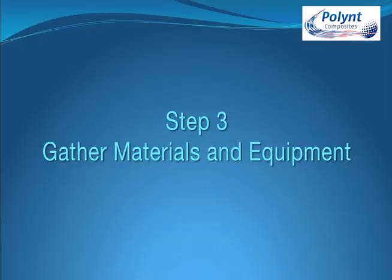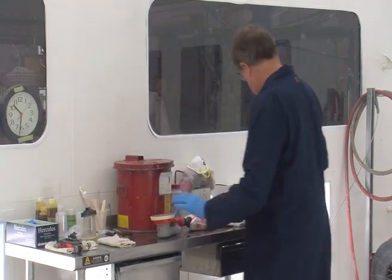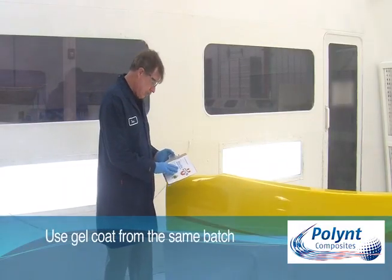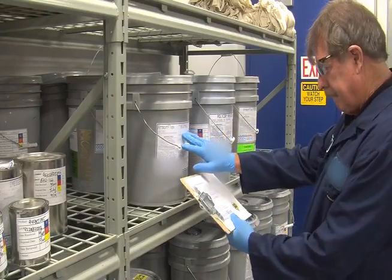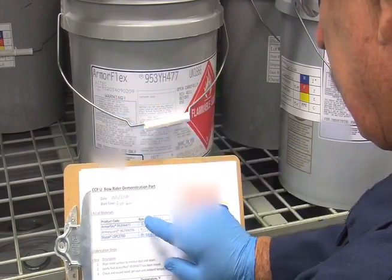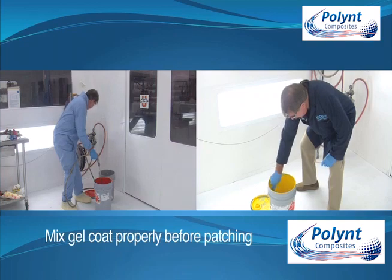Step 3. Gather the materials and set up the equipment. When possible, use gel coat from the same batch originally used to spray the part. Using a different batch for patching can result in off-colour patches. The batch number is shown on the label. Ensure that the gel coat in the container has been mixed properly before removing any for patching.